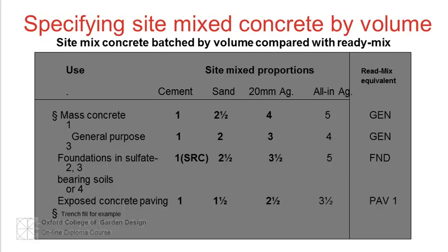The admix can be bought from builders' merchants and added to the mixing water strictly in accordance with the manufacturer's instructions. For backfilling of fence posts, use a mix not leaner than 1 to 10 with all-in aggregate.